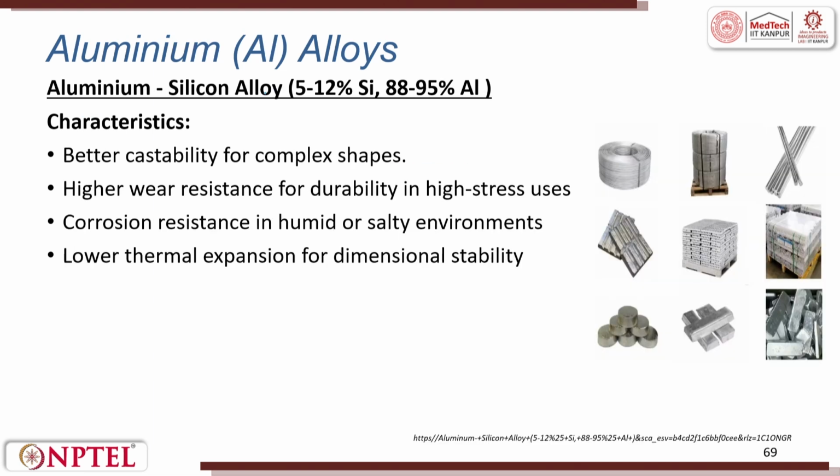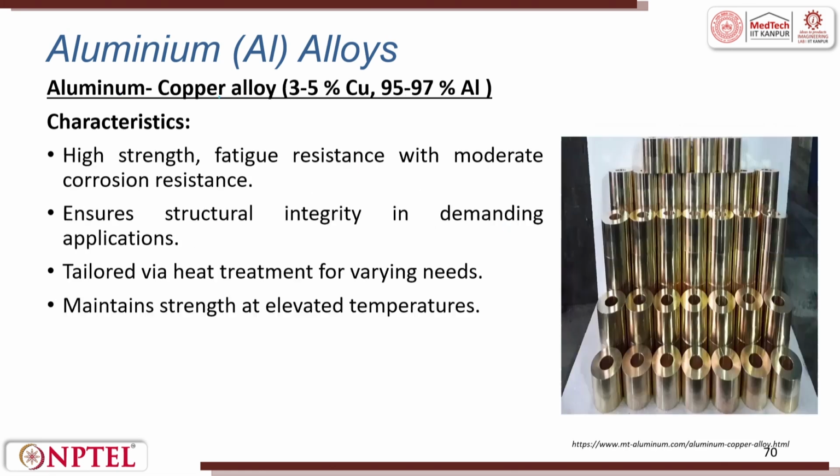Then aluminum silicon alloy also finds lots of application. Better castability for complex surfaces. It has very high wear resistance in high stress usage, corrosion resistance in humid as well as salty environments, low thermal expansion for dimensional stability. These are all a combination of aluminum with silicon.